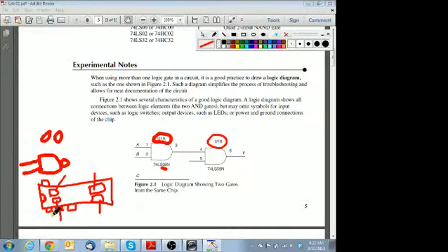Yeah, this is pin 1. Remember we talked about the tab. If the tab is here, then you go to the left of that tab and you count counterclockwise all the way around the part. So this would be 2, 3. So this 1 here is designating that this gate is actually connected to this pin 1. Or that this gate internal to that package is on pin 1. This 2 here is representing that that's pin 2. So that when the person is wiring this thing up, they're not going to see this nice little AND gate symbol when they're physically looking at the board. They're going to just see a package.